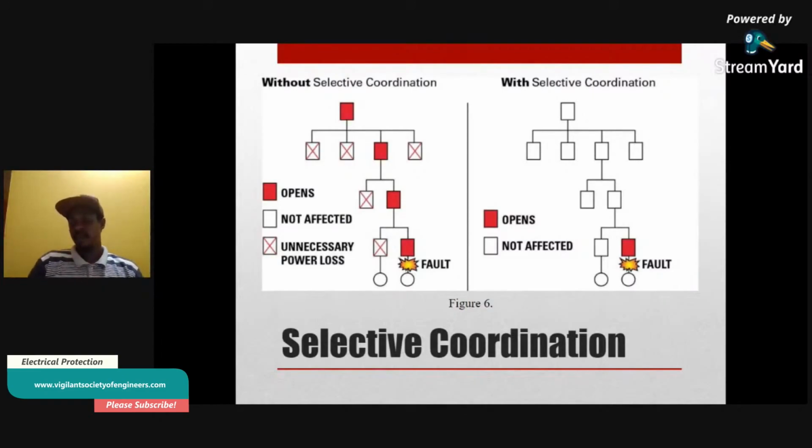So once a fault occurs in any one of the conductors of the branch circuit or the distributed system, then if a fault occurs at any point on the circuit, the breaker that is closest to that fault is going to be activated. So all the other circuits remain active, all right? And that bad portion that is affected is going to be isolated.